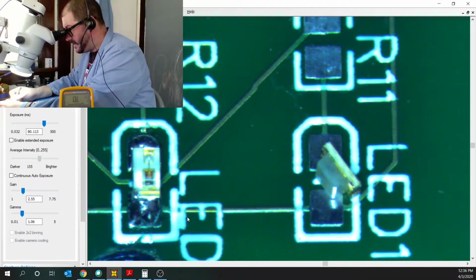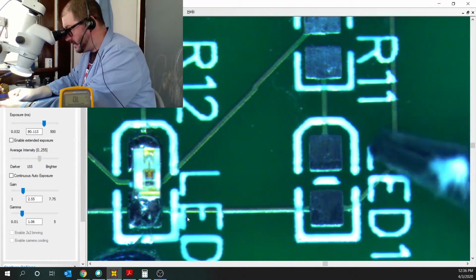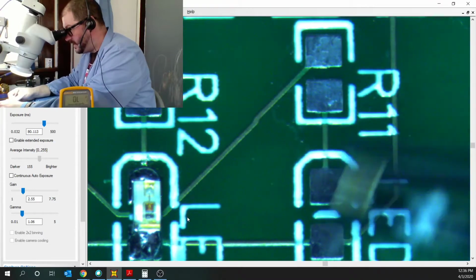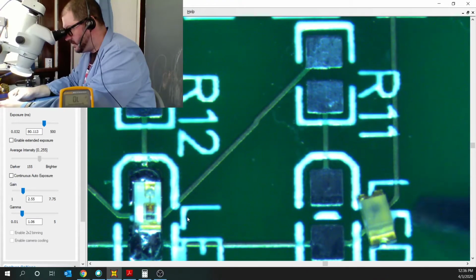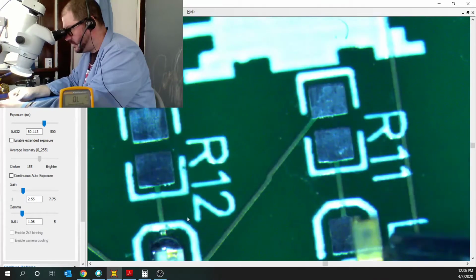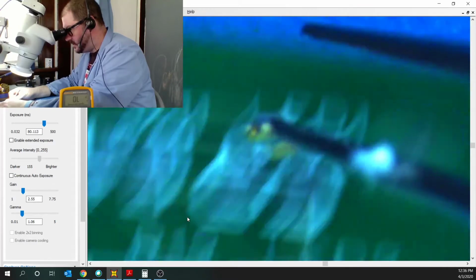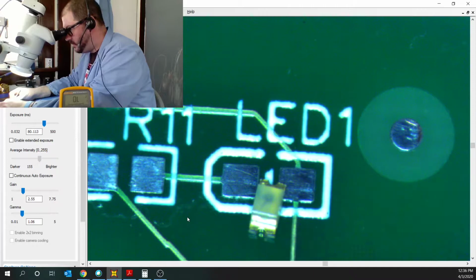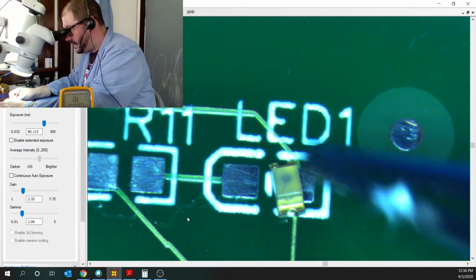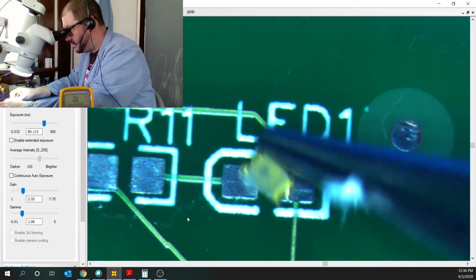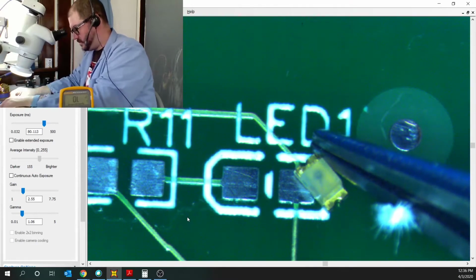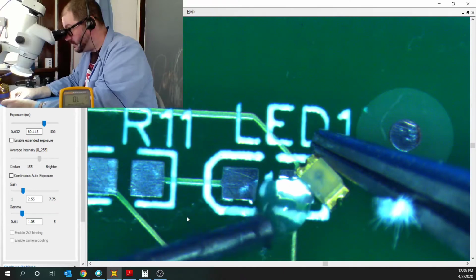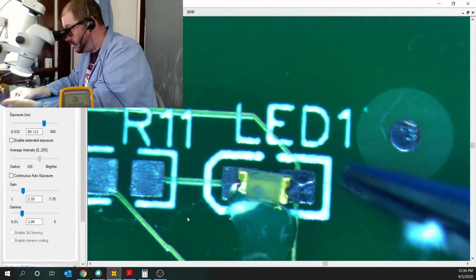But unlike the very bright colored King Bright LED that I've got for LED 2, LED 1, more or less, you can actually, if I turn this in just the right way, in fact, here, let me turn LED 1 so that you can see it in the left to right orientation. I'm going to put down a little bit of some fluxing agent because my tweezers have fluxing agent on them too, and this is just going to help to hold things into place.